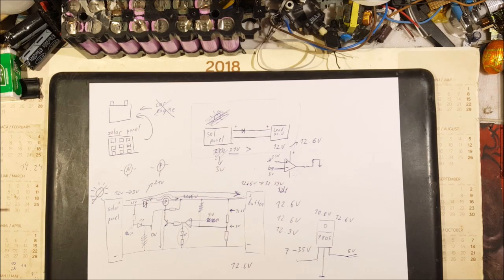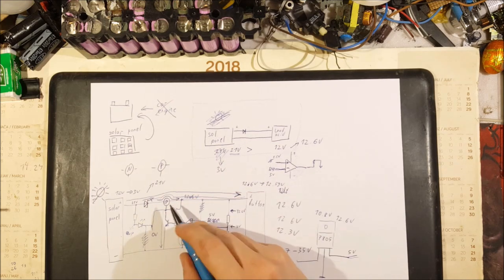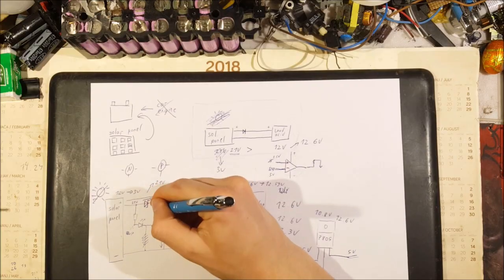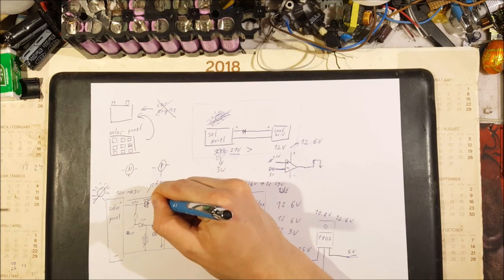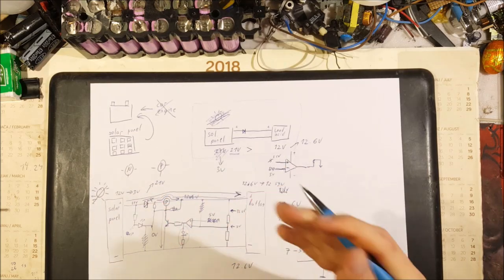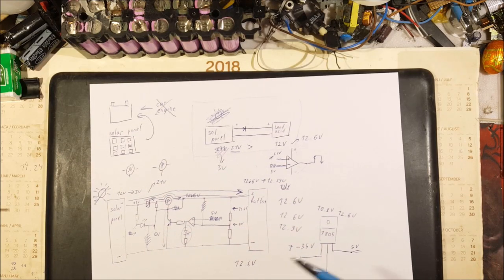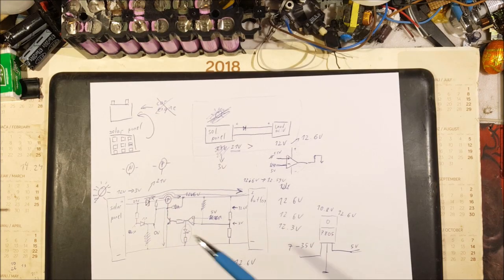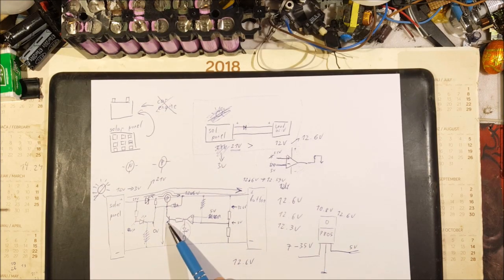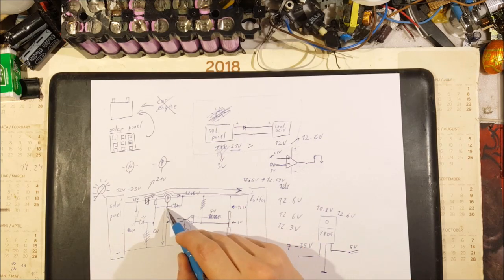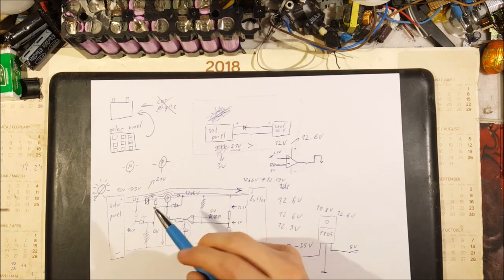So how do we fix that? Well, the simplest way really to fix this problem with this circuit is really just instead of this resistor right here, to put it right here. Now we still have the exact same effect of keeping this MOSFET turned off by default when this transistor is not open, because the voltage on its gate is pulled up instead of down.